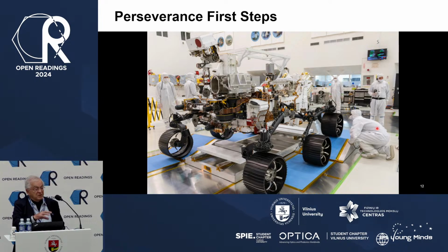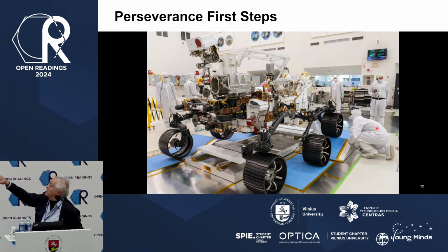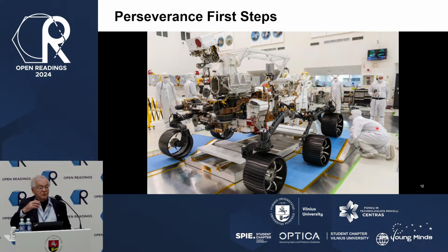And then to keep the inside electronics warm, this one, I think I missed mentioning to you, actually we use a small nuclear generator. So we use basically plutonium, and as the plutonium decays, we use thermoelectric couplers to generate electricity. That's how we generate the 140 watts. Fortunately, not all the heat is being used, so the rest of the heat, we actually circulate through the rover to keep the inside of the rover relatively warm despite all that change in temperature.